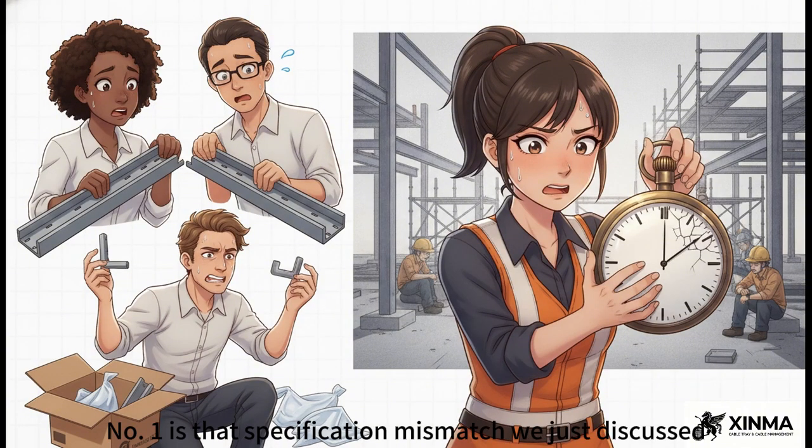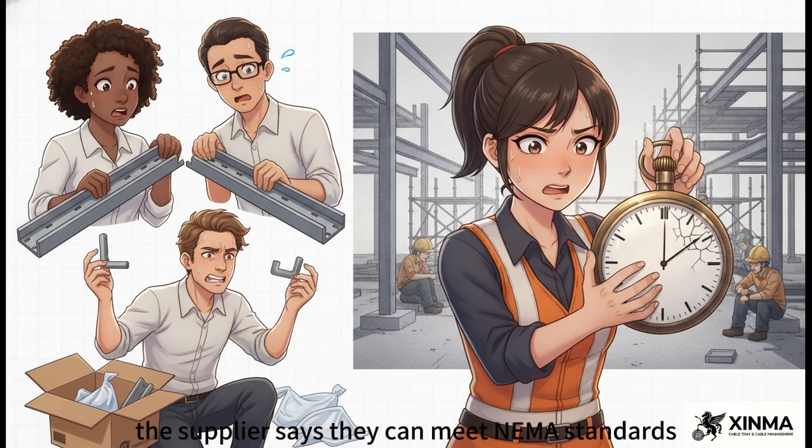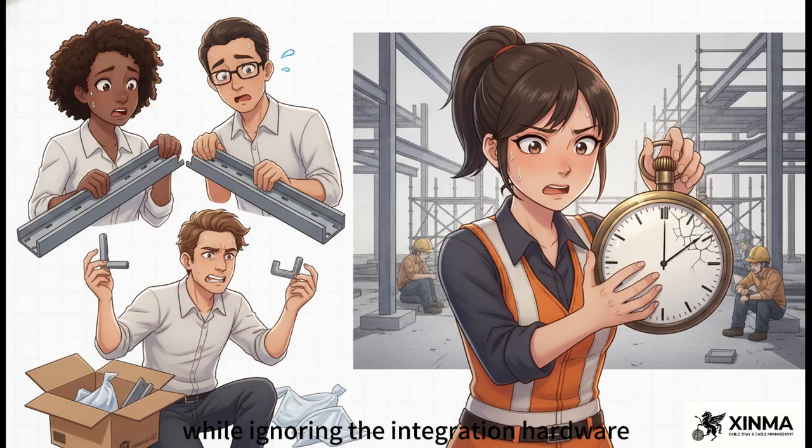Number 1 is that specification mismatch we just discussed. The supplier says they can meet NEMA standards, but they actually manufacture to local GB tolerances, meaning the part simply won't pass your site engineer's inspection. No way. Number 2 is missing accessories. Guys, it is never just the tray. It's the splice plates, the hold-down clamps, the seismic bracing. A supplier quoting just the straight metal tray while ignoring the integration hardware is 100% setting you up for failure. And number 3 is just the inevitable result of the first two, catastrophic site delays.